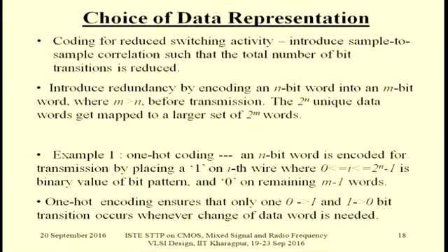That means the power consumed, see, whenever a transition is occurring, whenever a capacitance is switched, the bit line capacitance is switched, then only power is consumed. Okay? So that means the power that is involved is very small. In one-hot coding, the power that is conserved is very spectacular. But what is the downside? Downside is that so many wires are involved. Okay? So huge hardware increase is called for. So this is an extreme case.